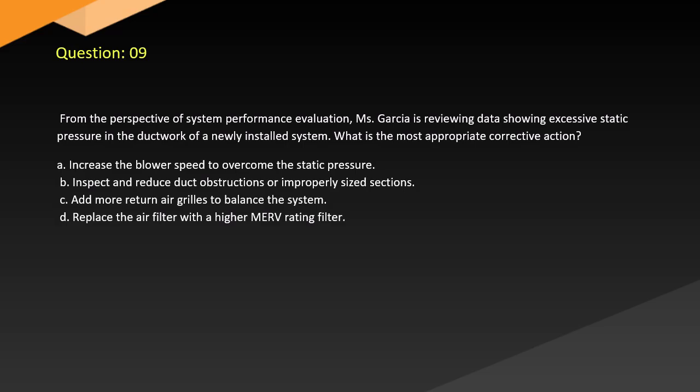Question 9. From the perspective of system performance evaluation, Garcia is reviewing data showing excessive static pressure in the ductwork of a newly installed system. What is the most appropriate corrective action? A. Increase the blower speed to overcome the static pressure. B. Inspect and reduce duct obstructions or improperly sized sections. C. Add more return air grills to balance the system. D. Replace the air filter with a higher MERV rating filter.